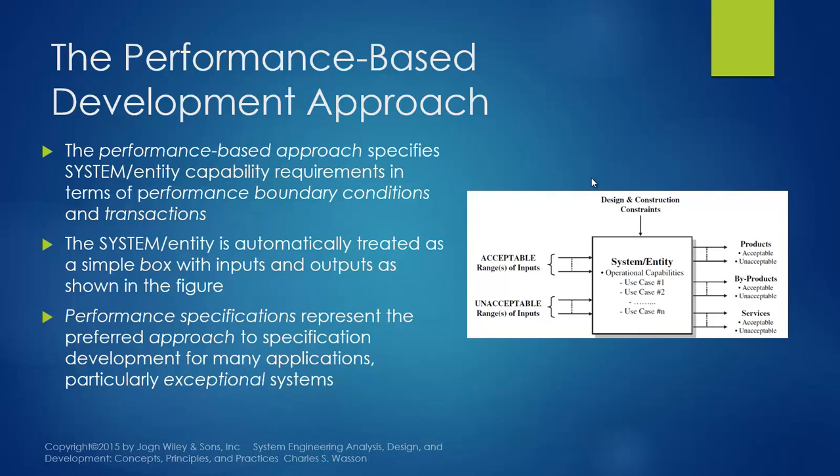An example of performance requirements: we have the detector that shall not contain foreign matter such as dust, dirt, fingerprints, or moisture that can be detected by visual examination. The reason is that it should provide criteria for compliance, which is assuming that foreign matter affects detector performance.